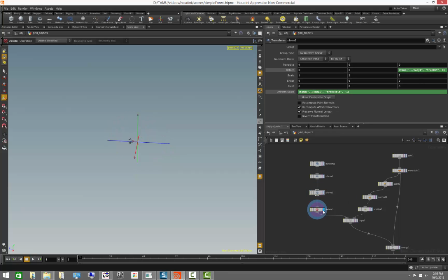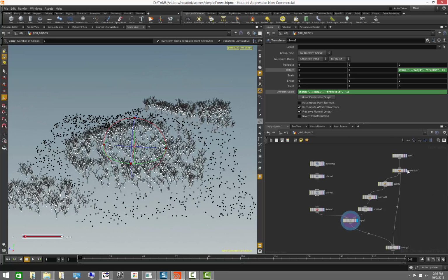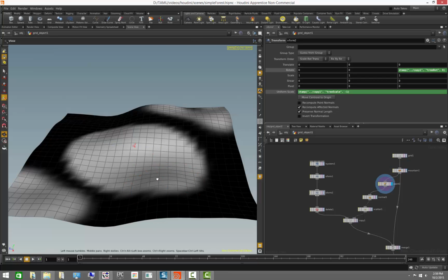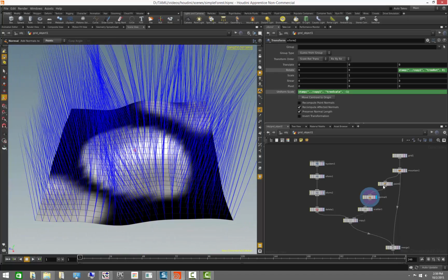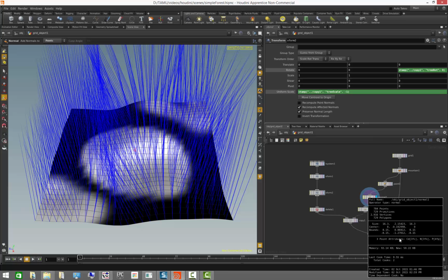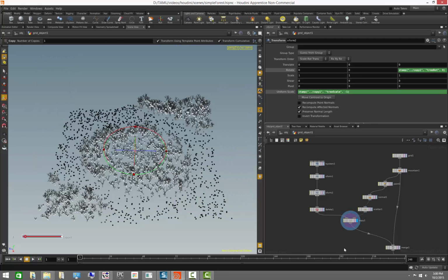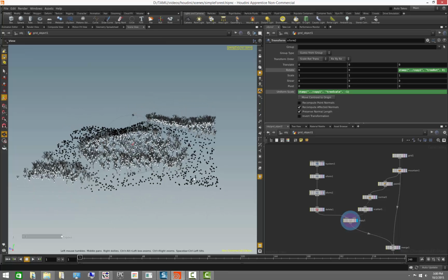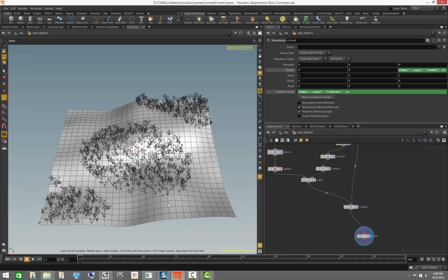Okay, so some of these things were controlled by stamping variables. We also learned a little bit about how we can use paint to drive the location of the points, as well as the normal sub to create normals, which we could use to orient the trees. So these operators created attributes which we're using to drive some of the operations. Okay, so the scatter node and the copy, which does the copy ultimately. We merged that with the terrain, and then we came back to this node. Cool.